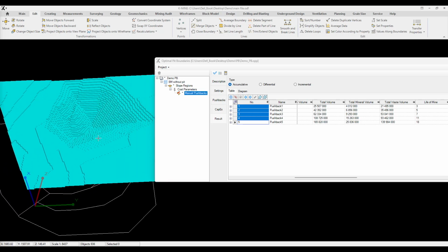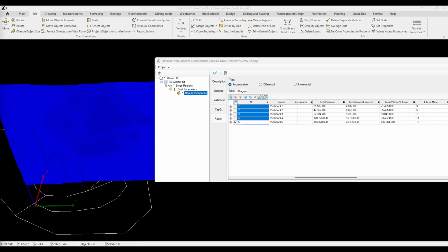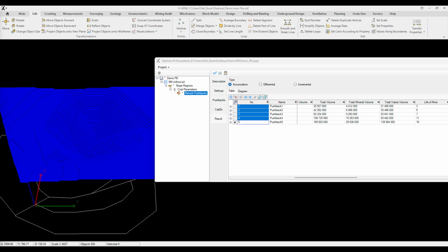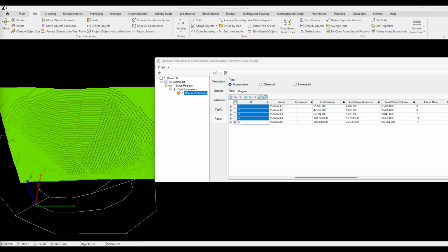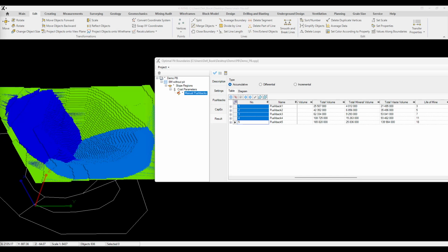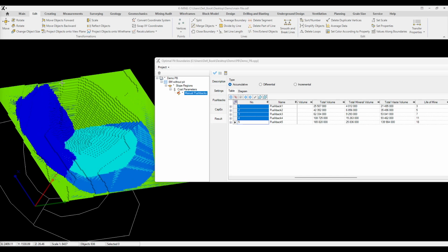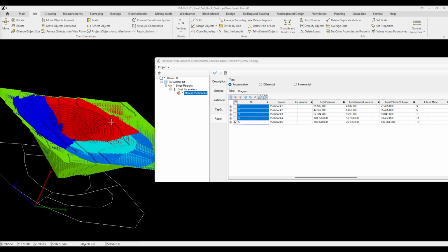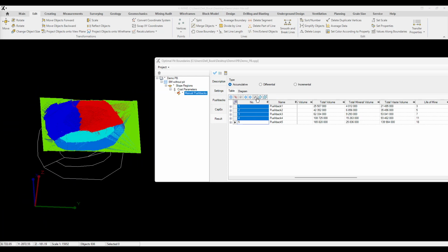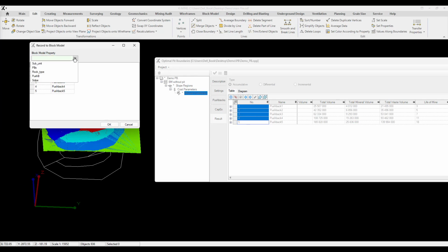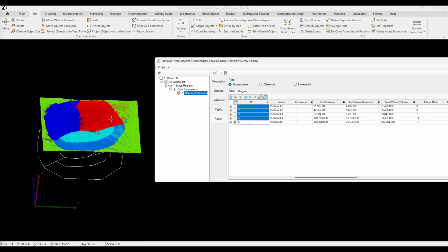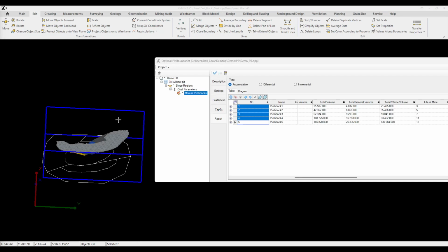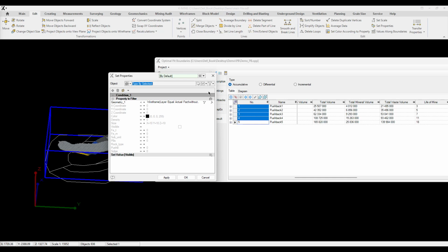There is no pushback without a wireframe, right? Let's create 5 wireframes that will correspond to each of the pushbacks. First, we select the ones we want and then click just one button to create all of them at once. When we finish with each pushback, each wireframe is a boundary. For better visualization, you can use random color in the wireframe settings in the Pit Optimizer module. So when you visualize wireframes by pushbacks one by one, you can find out more about the general mining sequence.